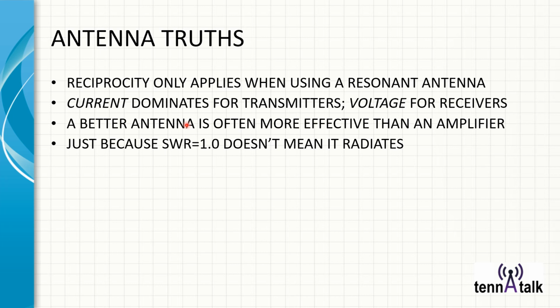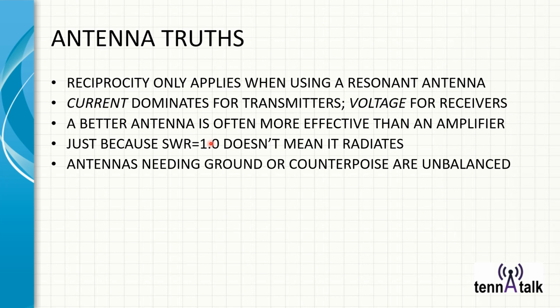Good example, a dummy load is an SWR of 1.0, and hopefully it doesn't radiate. It's designed not to. So that's a good indicator, but it's not sufficient to tell you that you've got a great antenna. Antennas need ground or counterpoise are unbalanced.